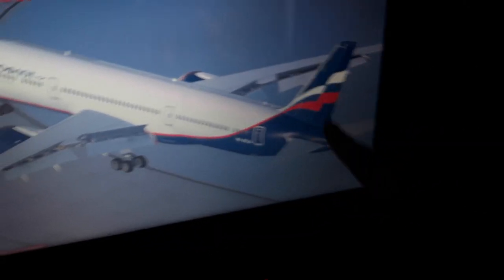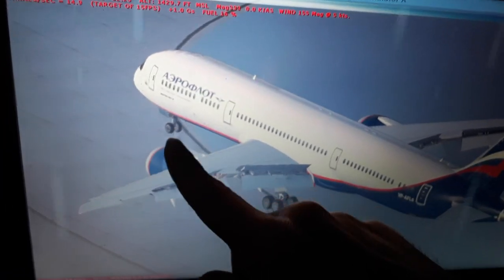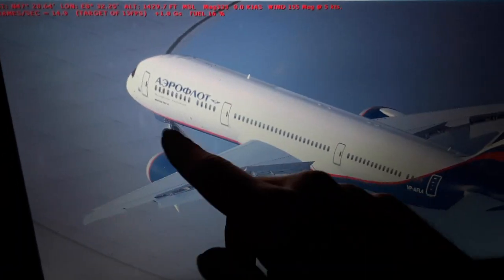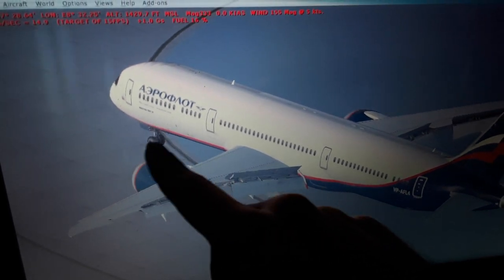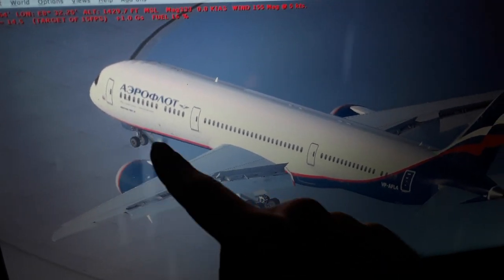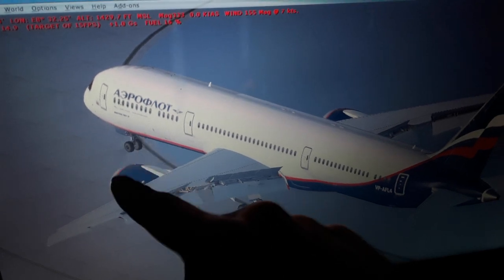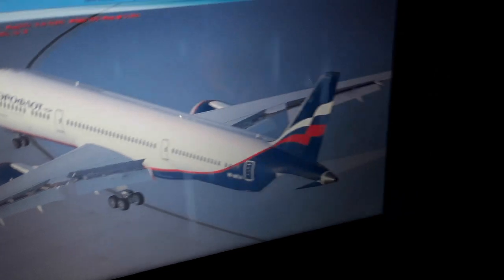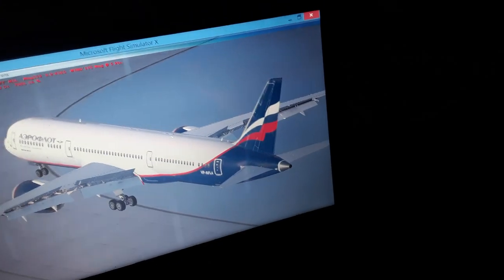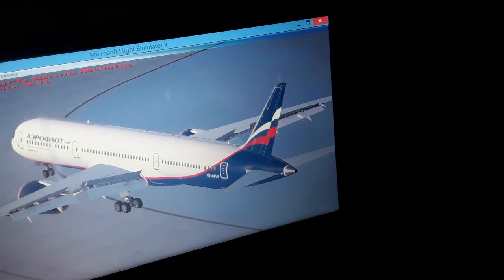So at 80 knots airspeed or 144 kilometers an hour, the forward nose wheel is locked to 0 deflection from the computer, or like half or 1 degree, very small deflection. Above 144 kilometers an hour or 80 knots, we have only the rudder to control the aircraft, both in takeoff and in landing.